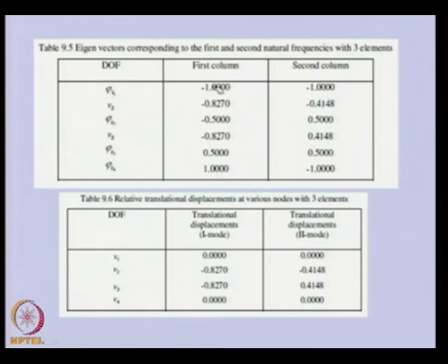If we want to obtain the first mode shape for translational displacement, obviously we need to pick up V2 and V3. Correspondingly we need to pick up this term and this term for linear displacement. Others correspond to the slope, but if we want the mode shape corresponding to the translational displacement, obviously we need to pick up these two. So we have picked up V2 and V3 here.